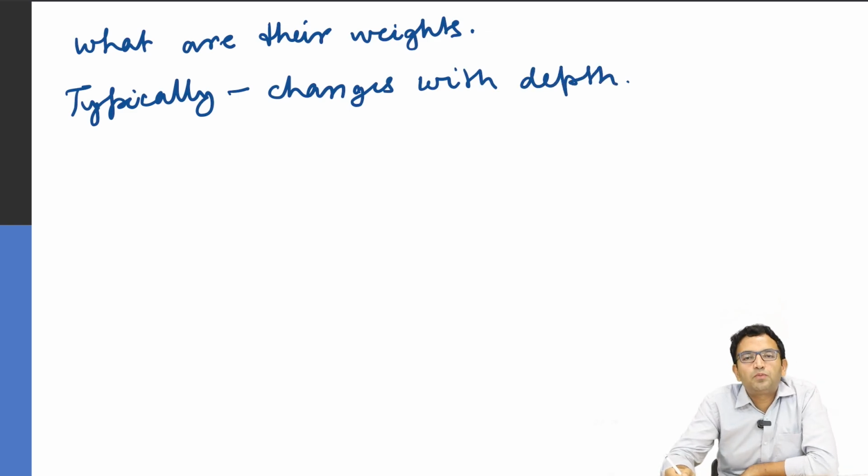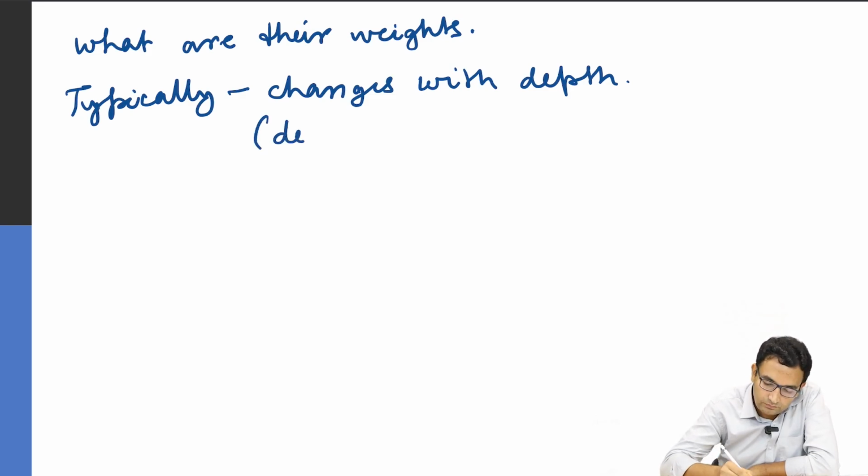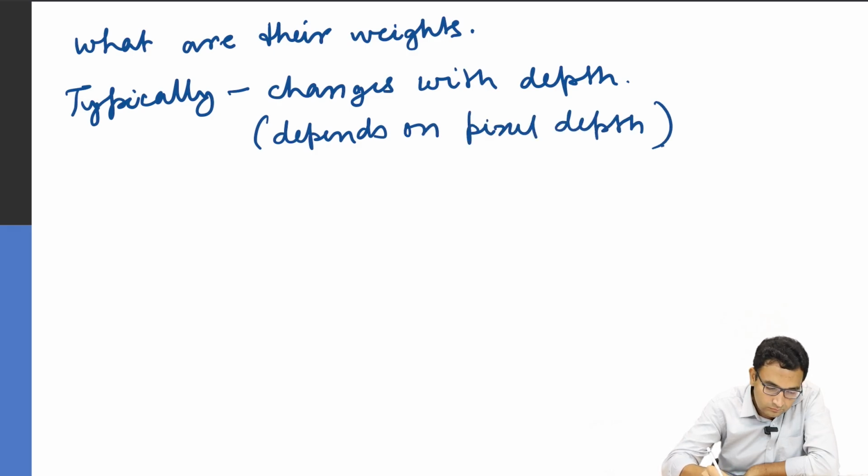This beam forming process is being done pixel by pixel, right? So as we are looking at pixels that come from shallow regions as well as deeper regions, we can choose to change the apodization, right? So apodization changes with depth. Why is that necessary? First of all, let's think about aperture.